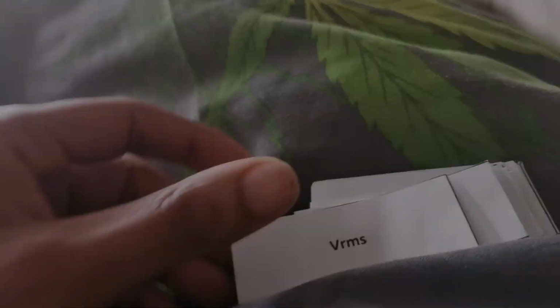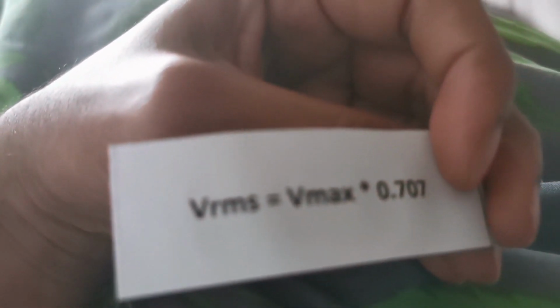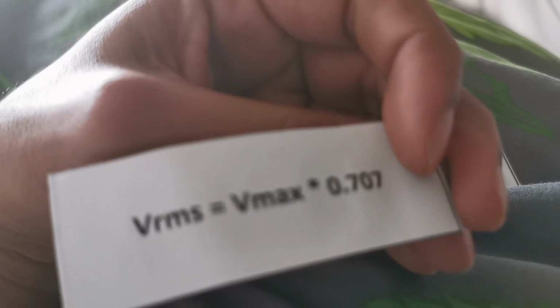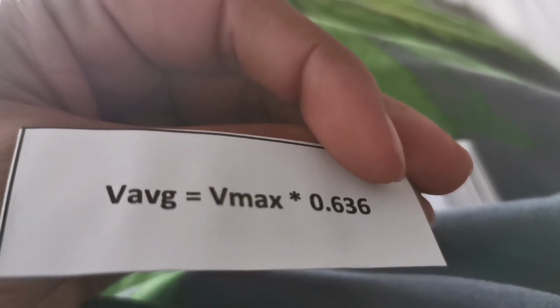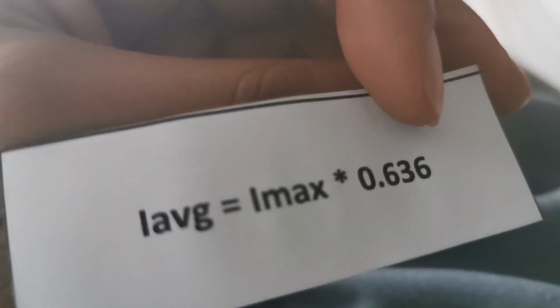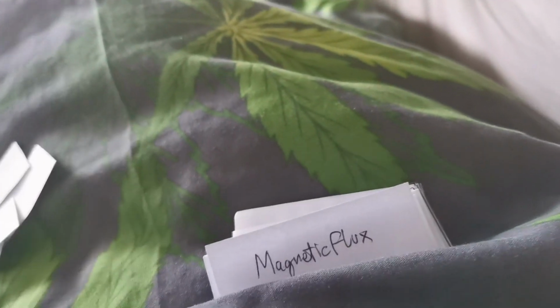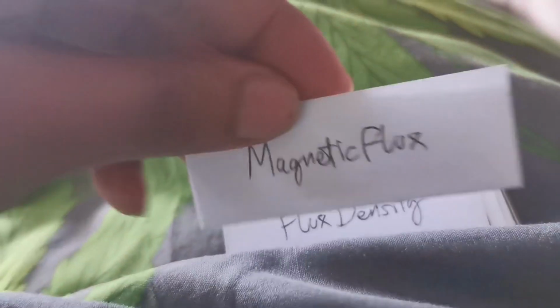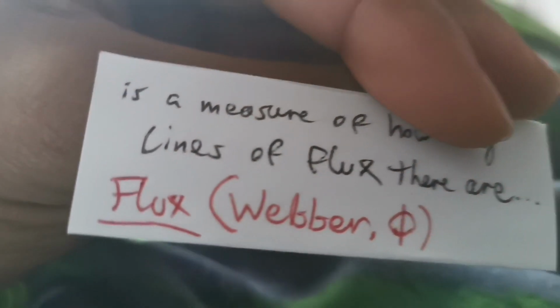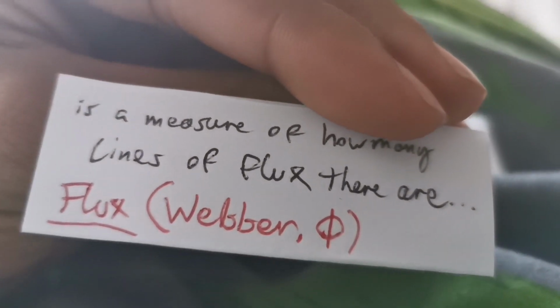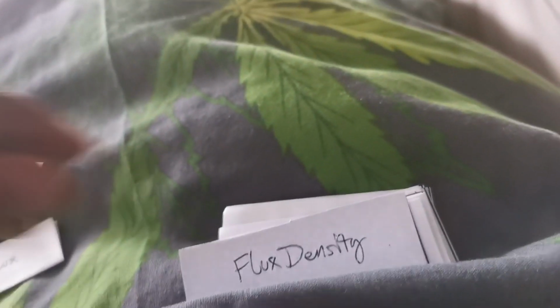The bigger the cross-sectional area, the less the resistance. The smaller the cross-sectional area, the higher the resistance. Temperature also will affect the resistance of the cable. The hotter the cable, the higher the resistance. The exception to this rule is carbon, being a semiconductor, which we know from previous presentations works the opposite way around. In other words, the hotter the carbon becomes, the better a conductor it becomes, therefore its resistance is lowered.